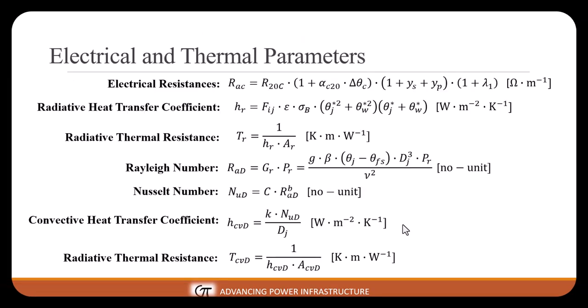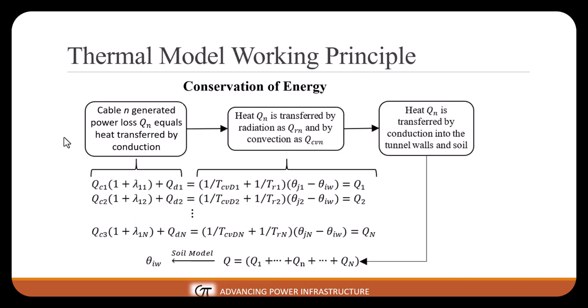I had used MATLAB to program this complex thermal system and used the IEC standard equations to compute electrical parameters such as AC resistance, including the skin effect and proximity effect parameters and the sheath loss factor. Also, I had used the industry-leading text, Fundamentals of Heat and Mass Transfer by Incropera, to compute thermal properties and thermal resistances of the system. Conservation of energy was used to solve this complex thermal system.